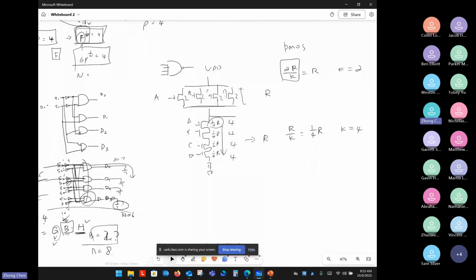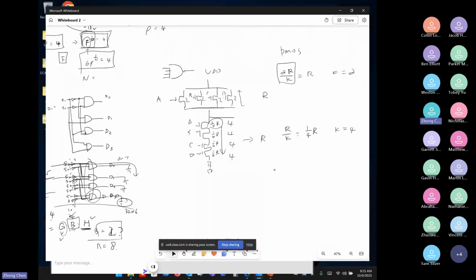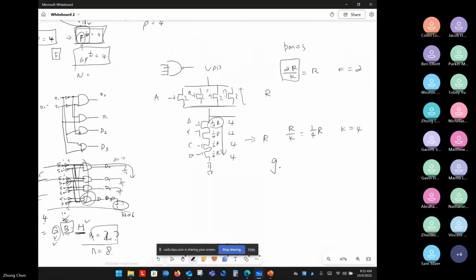Okay, so now you know there's a 4-input NAND gate, right? The transistor-level schematic, and you know the PMOS size and the NMOS size, so you should be able to calculate the G value here. So G2, because that is in the second stage, inputs, right? G2 is my total capacitance value.